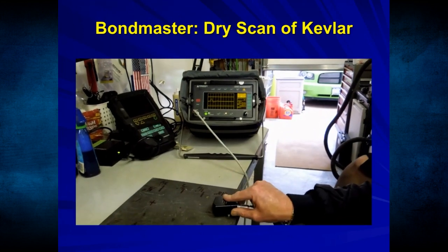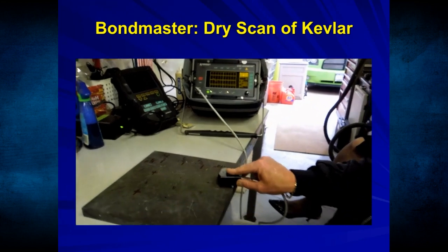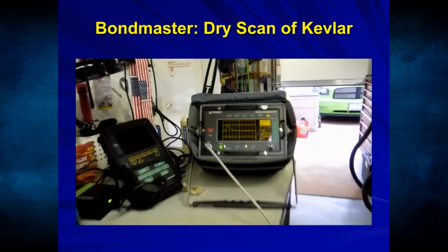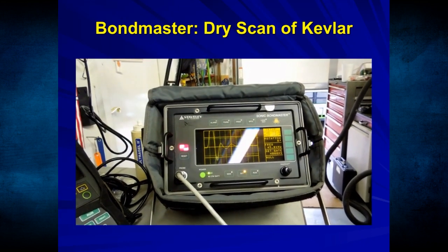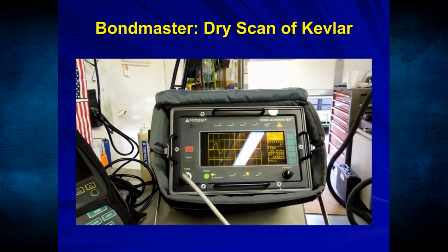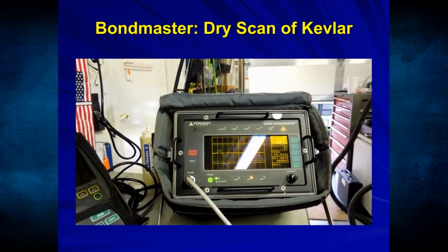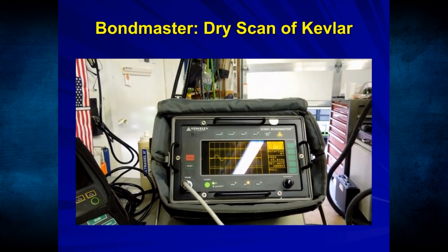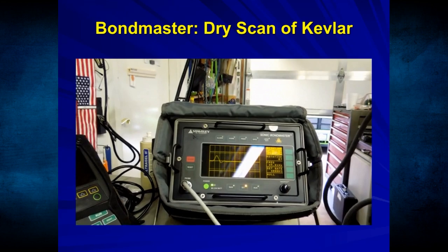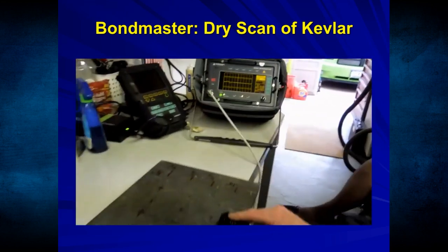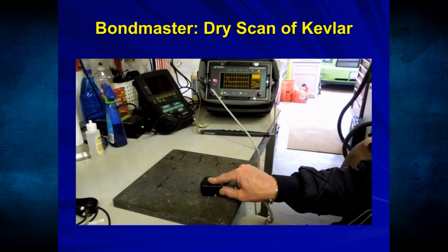Alright, there's your ½ inch holes. Your 1 inch holes. I'll do that again so you can see the screen. That's the 1 inch holes, and as the depth varies, let's go back to the ½ inch holes. As the depth varies, the height of the indication will vary, as well as the amplitude and phase change. And in the 2 inch holes. Whoop. Bingo.